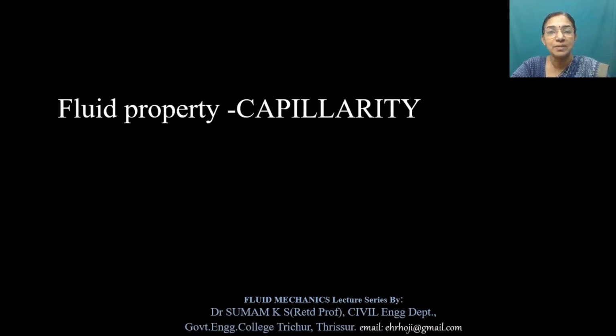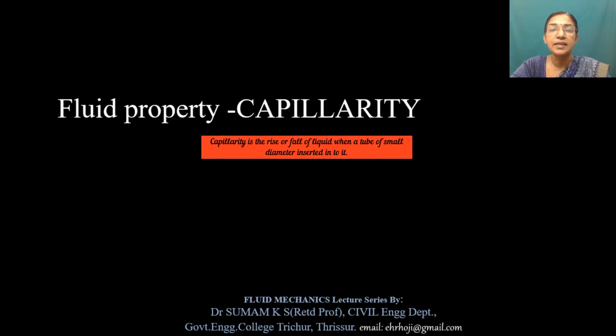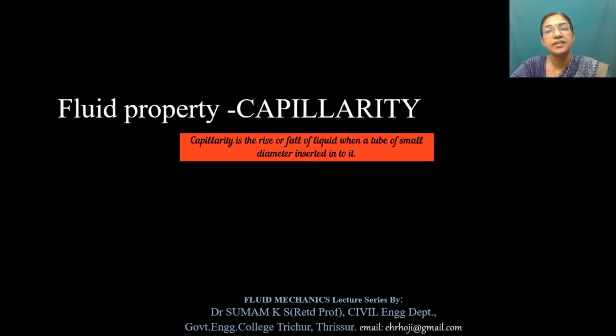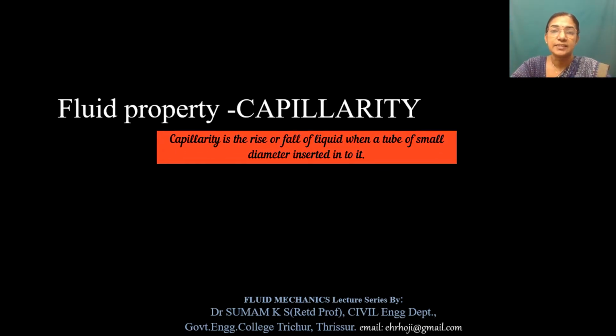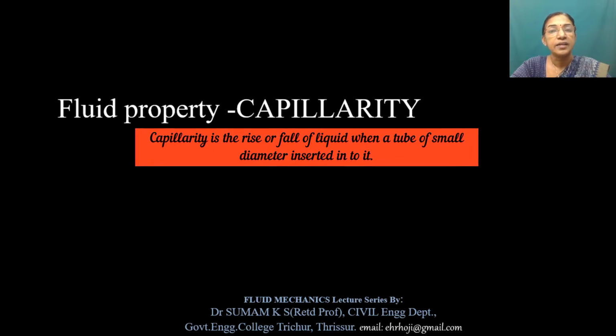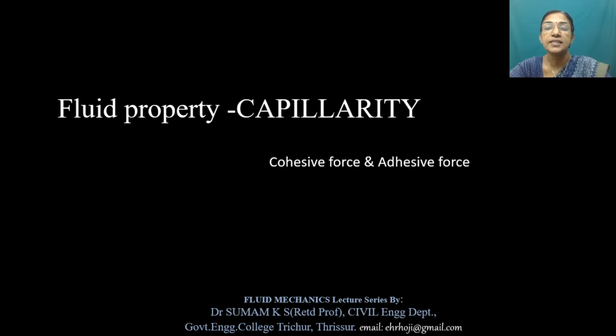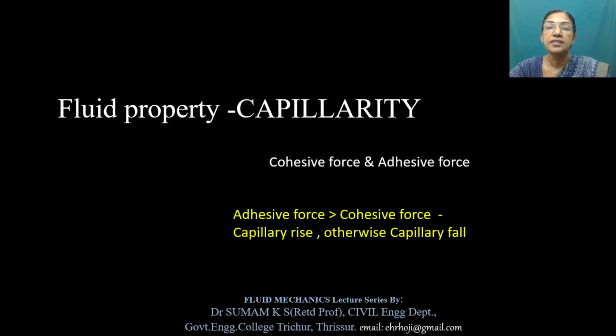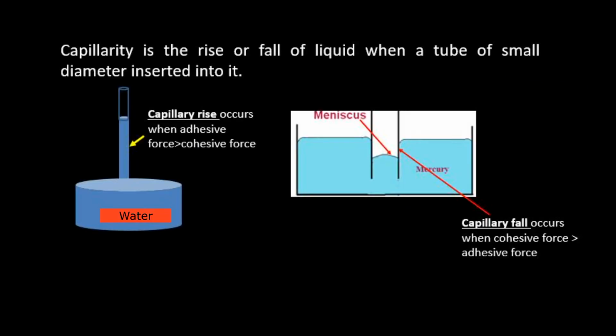I am your Suman. Today we are going to discuss capillarity. It is a consequence of surface tension. Basically both surface tension and capillarity depend upon the atomic structure of the fluid, and it is also different for different fluids. The major forces governing this phenomenon are cohesive forces and adhesive forces. If the cohesive force is more, we can see a capillary fall, or if the adhesive force is more, we can see a capillary rise.